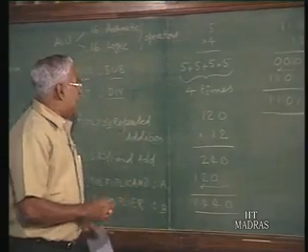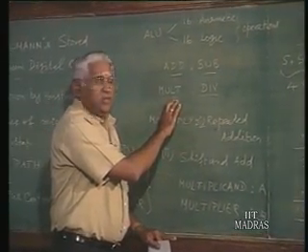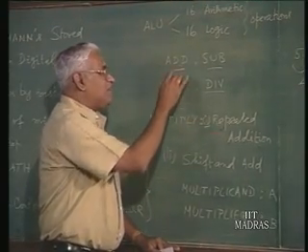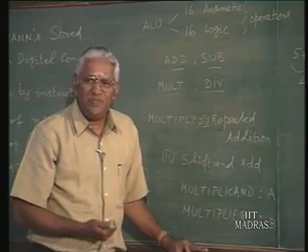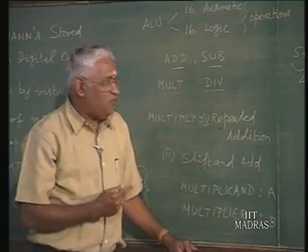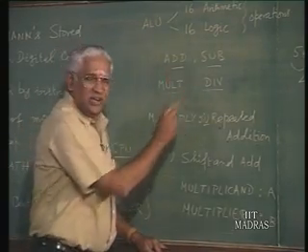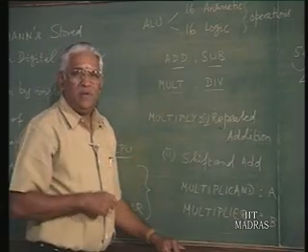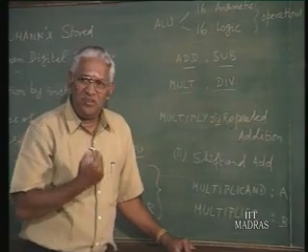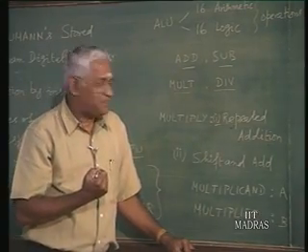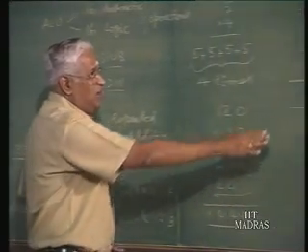So, we need not really add the necessary arithmetic circuits or units, because just like multiplication is repeated addition, division can also be looked at as repeated subtraction. But there is an advantage if you have a special hardware circuit, let us say for a multiplier or for a divider, because this way the implementation will be faster. Anything done through software means step by step, and step by step would mean more time, right. Whereas here you can see that it will be done much faster.